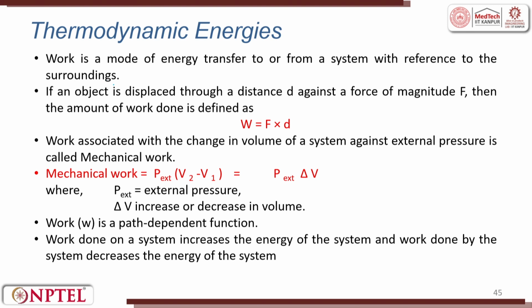This is always compared to the surrounding. If an object is displaced through a distance d against a force of magnitude F, then the amount of work done will be written as W equal to F into d. The work associated with the change in volume, if you go back to the piston example, you will see V1, V2, change in volume, delta V. The work associated with the change in volume of a system against the external pressure is called mechanical work.